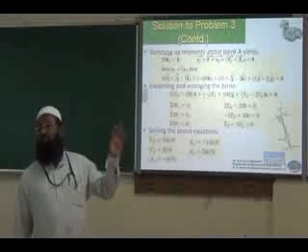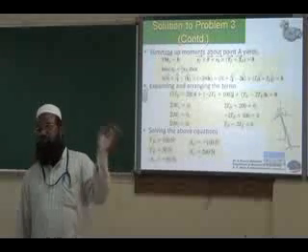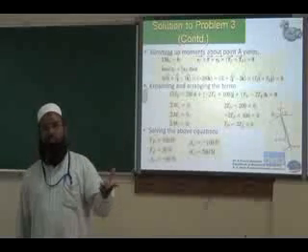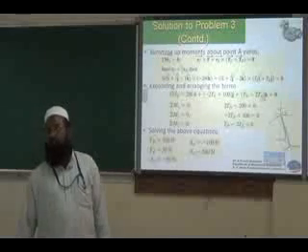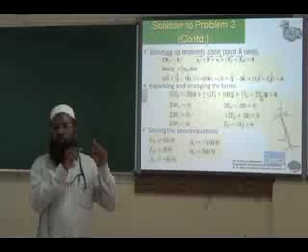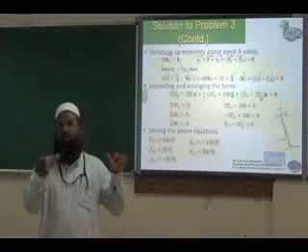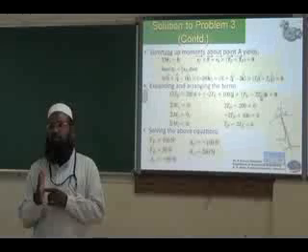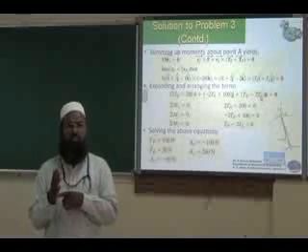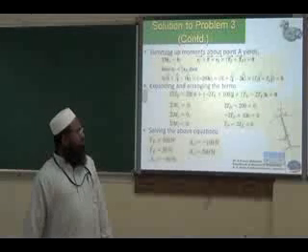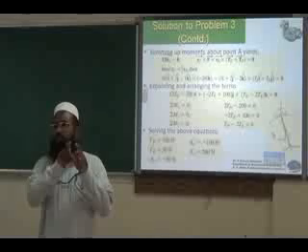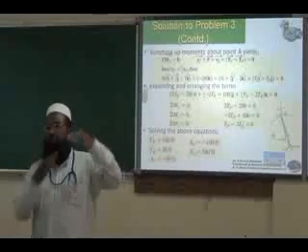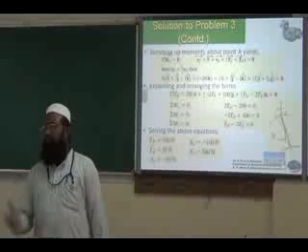So here the scalar method cannot be applied because the rod is in space. We have to apply the cross product concept. So for that, we first convert all the forces into Cartesian form, then use the cross product concept. With the cross product, transmissibility applies, so the position vector from any point on the line of action of the force need not be perpendicular. That is the advantage of using cross product. For finding the moment with the scalar approach, it should be a perpendicular distance from the particular axis. But that is difficult because the rod is in space and its angle is not given. The angle will be difficult to find.